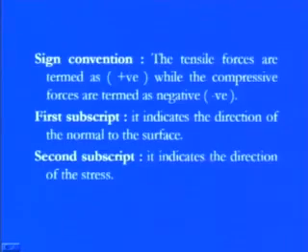So if we are talking about the normal stress component, then we always choose the tensile stress as positive and the compressive stresses as negative. But if you go back to this concept, we found that whether you are working in the x domain, y domain or z domain, the stress components were, in the x domain, sigma xx, tau xy, tau xz.